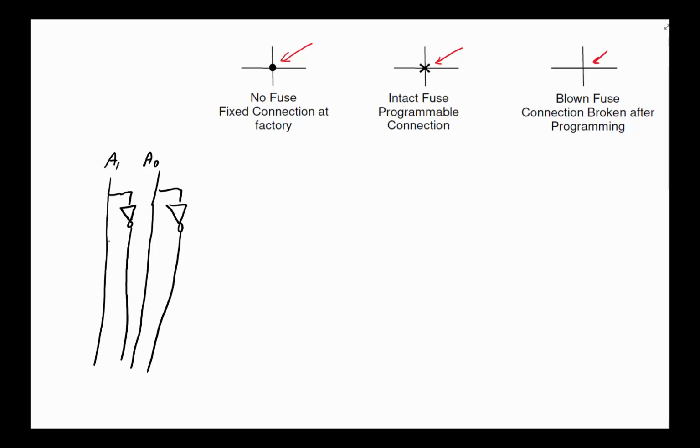And then you will have this line that is drawn to an AND shape. In reality, this one line actually represents four separate lines. Usually it is because we have two inputs and four possibilities, the non-inverted input and the inverted input, and we might want to make a connection to any of these four. They give you four lines, but for simplicity of drawing, they always draw it as a single line. And then typically there are as many ANDs as there are minterms.